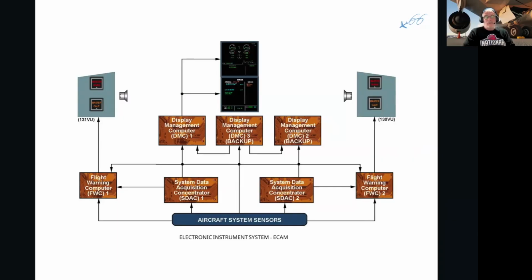That's what made it such a robust aircraft, where invariably there are 3 systems of everything. Number 1 system is dedicated for the captain's side, and number 2 is dedicated for the co-pilot, first officer side, and number 3 is in hot standby and is switchable to the left, to the number 1 position, or to the right, number 2 position, if that one fails.